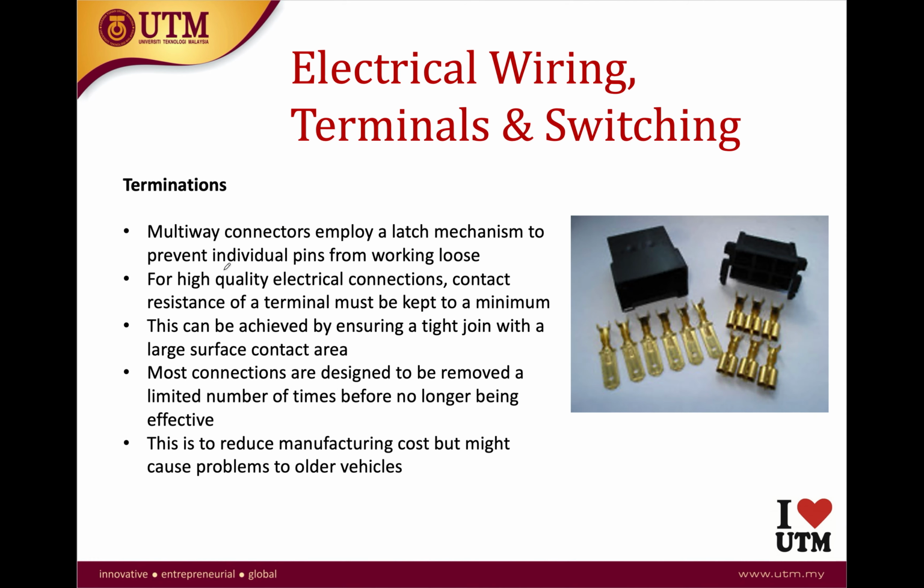Aside from that, you have multi-way connectors that employ a latch mechanism to prevent individual pins from working loose. For high quality electrical connections, the contact resistance of the terminal must be kept to a minimum. This can be achieved by ensuring a tight joint with a large surface contact area between the terminals. By using these multi-way connectors, you can also reduce manufacturing costs, which might basically be a problem for older vehicles.